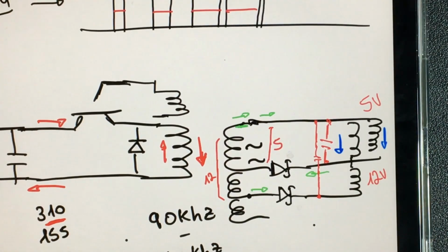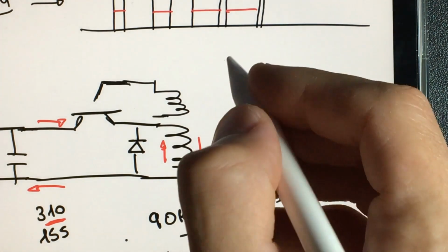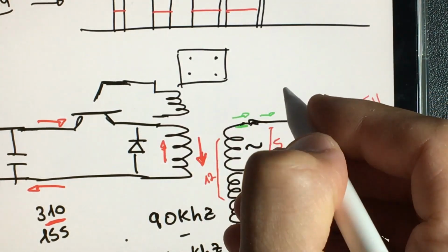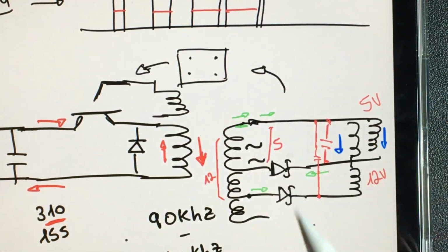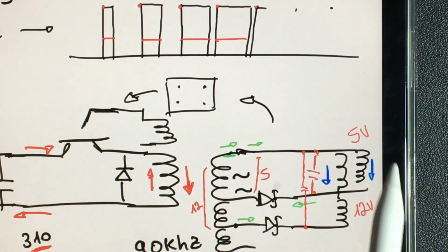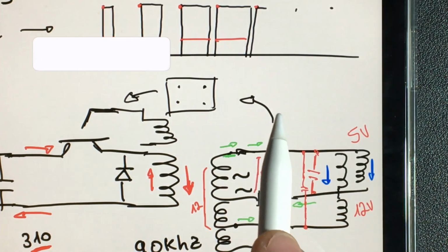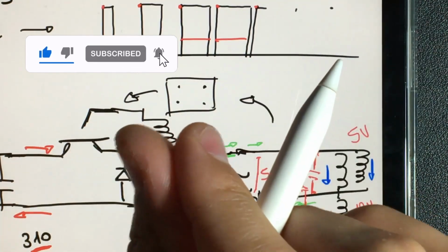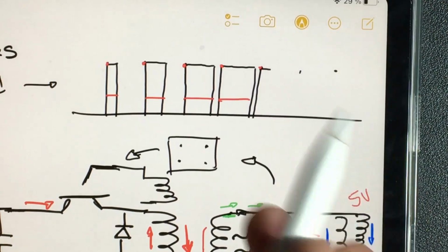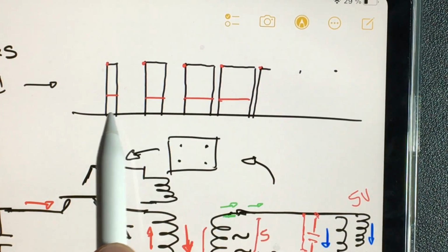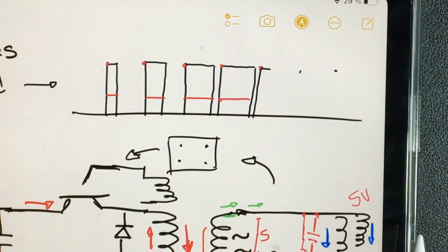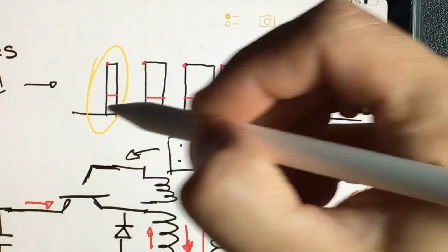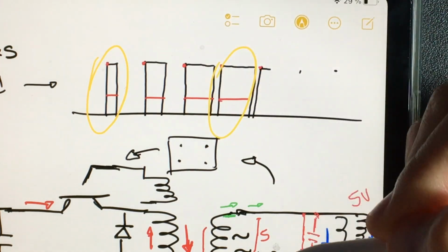So, through a notice that the switched mode power supply has at this point, through an element that is warning or communicating from this side to this, it is informing the switch if more or less electricity is being consumed. Then it tells him how wide he has to pulse, the speed of it. But what is going to vary is the pulse width, the width of the wave that goes up, that is the one that is used. If it is being used less at that moment, it delivers less. If it is used more, it delivers more.